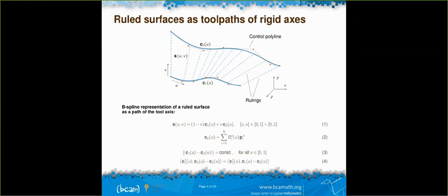But because we are at the finishing stage, the tool is completely on the workpiece, in full contact, and the motion is very well controlled. So the assumption of having constant ruling lines here is a correct assumption in reality. I agree with your opinion, but in our case we have full contact of the tool and workpiece. It means that we have constant rulings. Okay, I understand what you're doing.